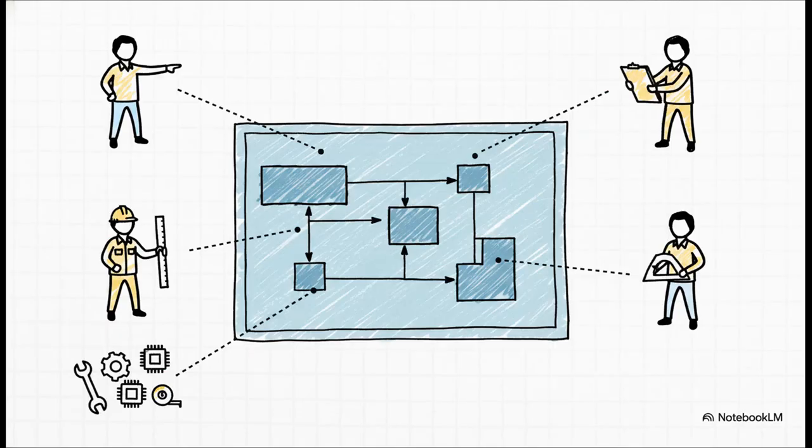And that first phase, team formation, is totally non-negotiable. A HAZOP's success lives or dies based on the people involved. You absolutely need an objective facilitator, someone to write everything down, the engineer who knows the design inside and out, and, this is so important, the plant operator who knows how things actually work out there on the floor. It's that blend of book smarts and real-world experience that makes this whole thing so powerful.